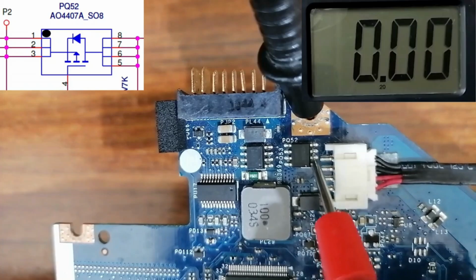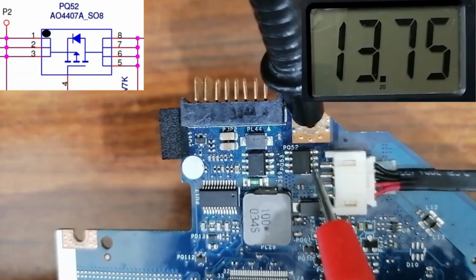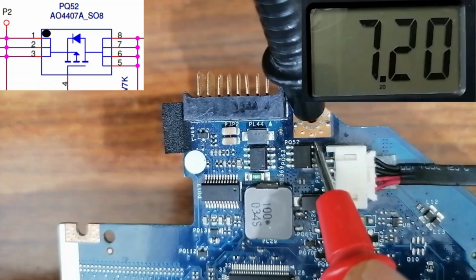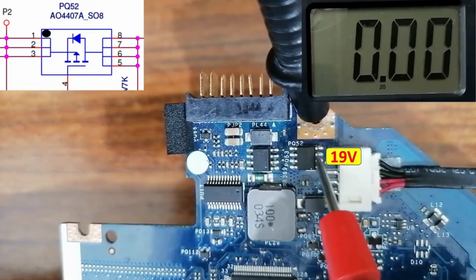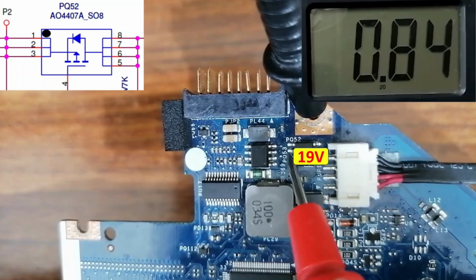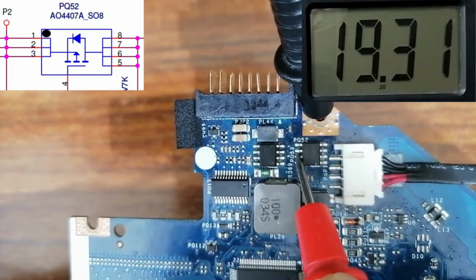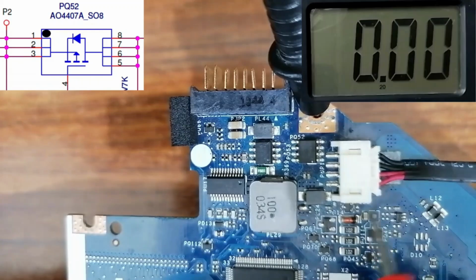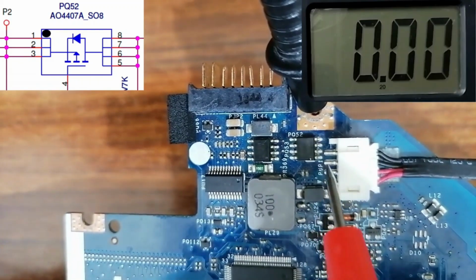So once we have 19 volt here in the source, and we have 8 volts in the gate as the control signal, 19 volt should pass to this side, to the drain. Let's check the drain. We have 19 volt, as you can see. So the 19 volt, or the VIN, is good for this motherboard.